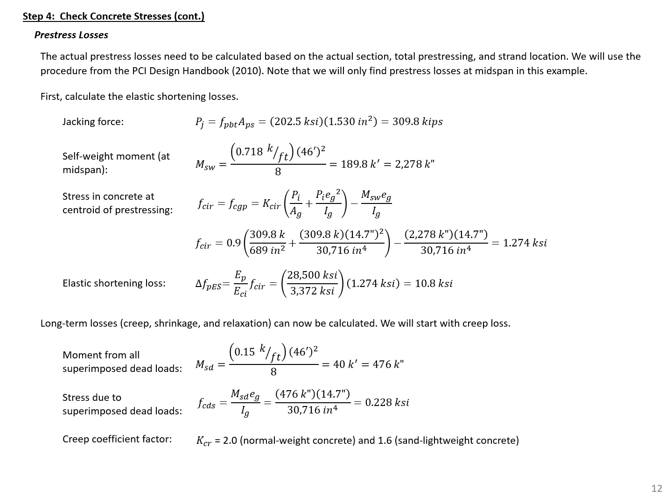Next, we need to calculate our actual pre-stress losses for the section that we're analyzing. So we're going to use the PCI Design Handbook approach, which is the approach that you'll typically use for building members. In this approach, we calculate an elastic shortening loss and then a creep, shrinkage, and relaxation loss. I'm not going to go through this in too much detail. We've covered it in previous examples, but I'll provide it here so you can look through it if this is new to you.